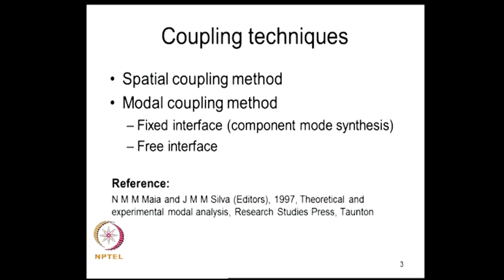Often a large finite element model may be needed to take into account geometric complexities of the structure, and a very detailed modeling may perhaps not be needed if one is interested in capturing the behavior of the system. A simpler model can capture the spatial variation of the system behavior, but a finer model is needed to capture all the geometric details. So, in which case there is no point in working with a very large model, a smaller model would suffice.